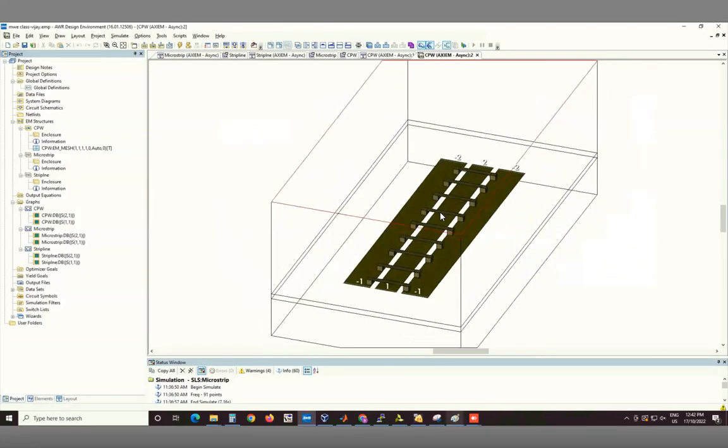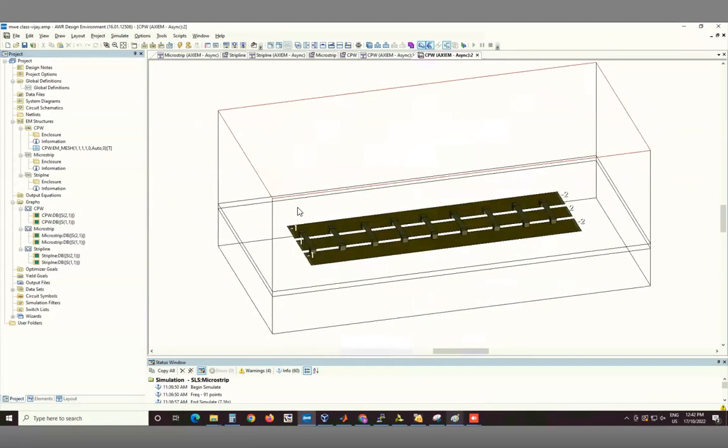This looks sort of reasonable, but here there is a potential problem. The gap here is about 50 microns. This height is 100 microns right now. So this is going to now feel the presence of the ground plane because of this connection as well. Not so much. If it was continuous, it would be even worse.